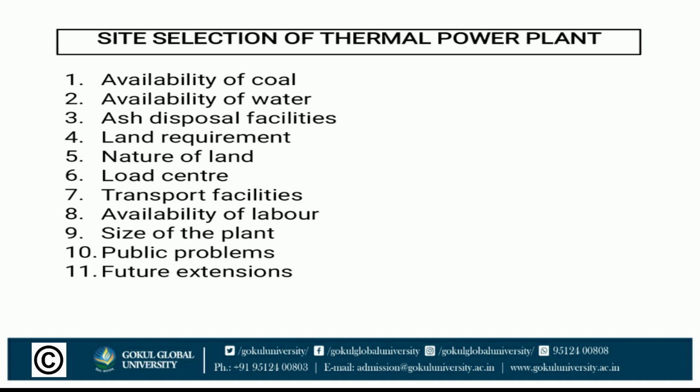Also, if the plant is located away from coal mines, it may create problems due to failure of the transportation system or strike at mines, etc. For these reasons, a considerable amount of coal, at least 15-day coal supply, must be stored at the power station. However, it increases space requirements, staff, costs, and losses of coal storage. In case it is not possible to locate the plant near the coal mines, then the plant should be connected to the railway.